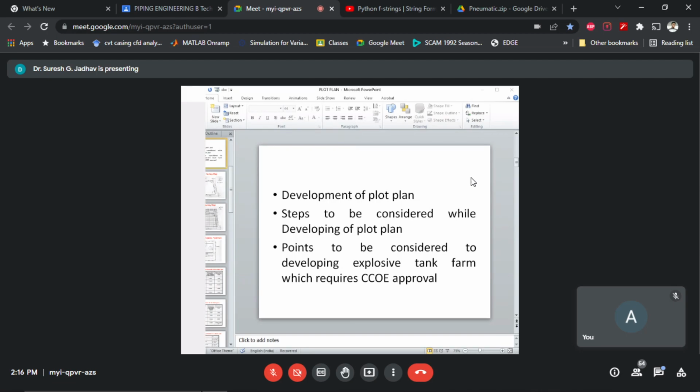The fire point is usually a few degrees above the flash point. Flash point is the minimum temperature at which a liquid forms a vapor above its surface in sufficient concentration that it can be ignited. Flammable liquids have a flash point of less than 100 Fahrenheit. Liquids with lower flash points ignite more easily. So these are the criteria regarding flash points.